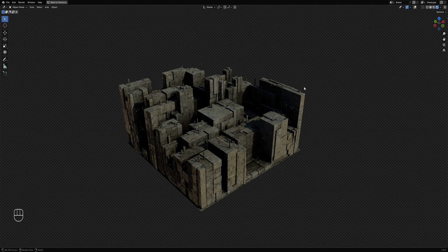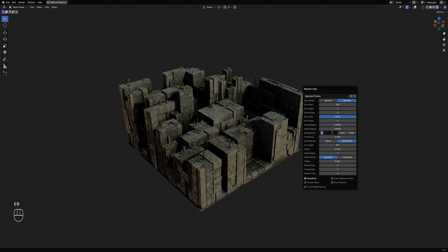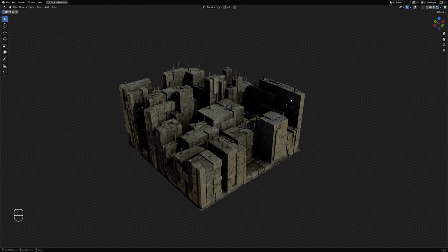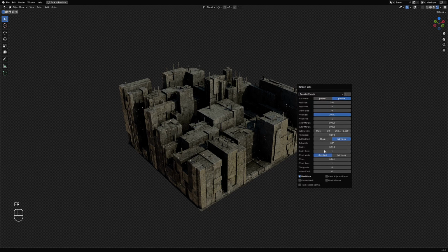It's probably still too big. Just be careful with the cuts as you increase it. Okay, probably just stay around 30. My advice, if you're unsure with the subdivision and the pole size and you think it may freeze Blender, save first before attempting to use a higher value.